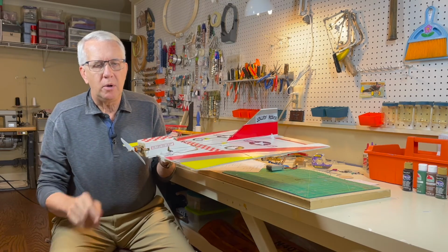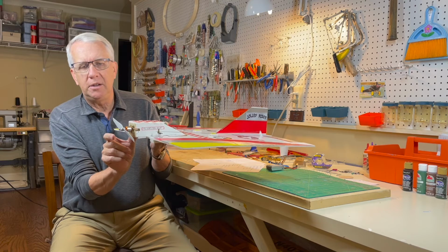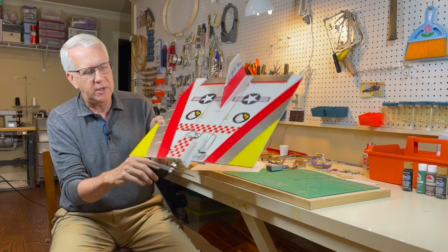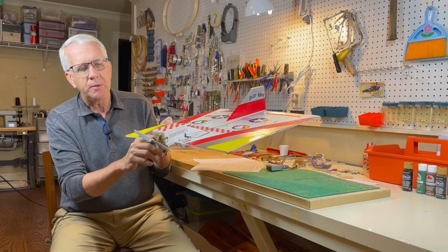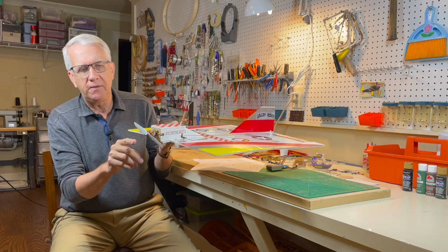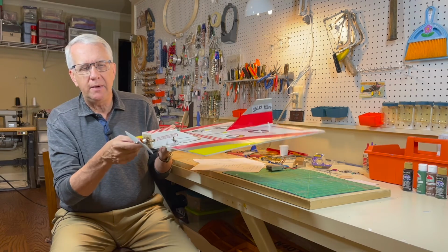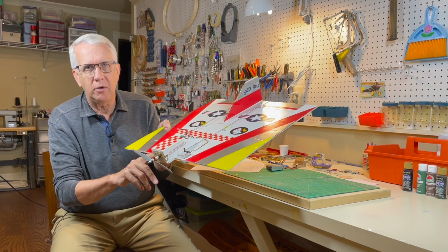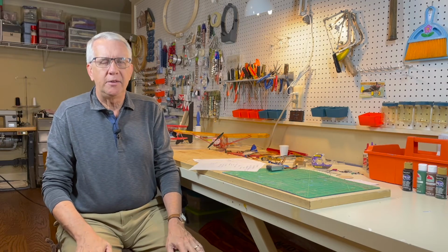To save the weight of the bolts, what I could have done on this is extended the nose out another inch or two, because remember, the length of the nose has nothing to do with the center of gravity location. It's just the shape of the wing. By having the motor a couple inches further forward, I might not have needed the bolts to achieve the center of gravity, and had a lighter aircraft. Remember, whenever we build and fly our model airplanes, we want to do anything possible to reduce the weight. So by extending the nose to try to achieve the center of gravity without adding extra weight, that's to your advantage, just to have a lighter flying model.